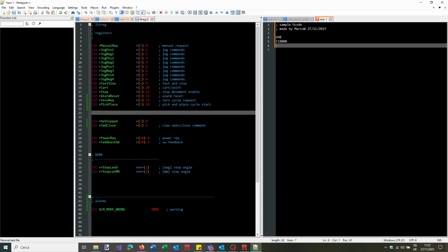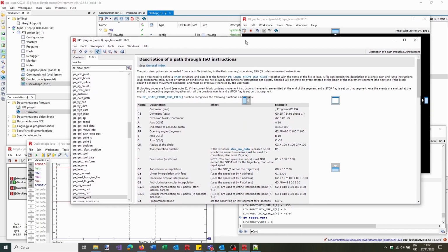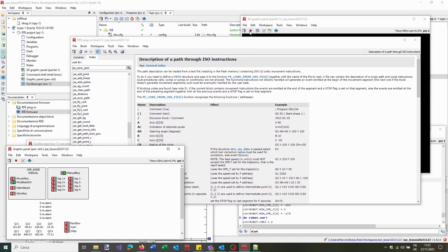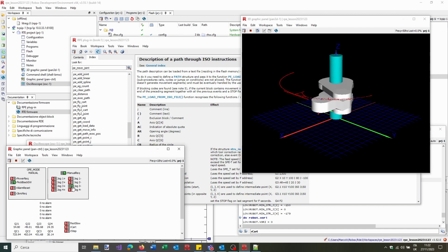And now here we do a G00, which is a fast move, and so we can write. We would like, again, the first move, for example, to be a move to some kind of X, Y, and Z. Let's go to a comfortable place, like here, and then, for example, we would like to stay here, a little higher, okay? Yeah, like this. So it's almost 360.